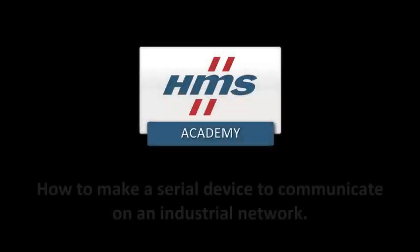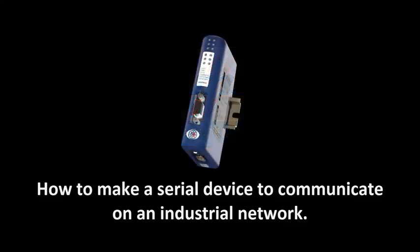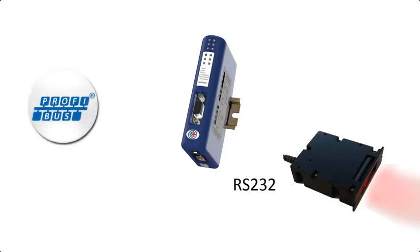In this demo, we will show how to make a serial device communicate on an industrial network. To do this, we will use the Anybus communicator as a gateway. In my scenario, we have a barcode scanner using RS-232, which I want to access from a PROFIBUS network. I've connected the barcode scanner to the bottom interface of the Anybus communicator and the PROFIBUS cable to the front.